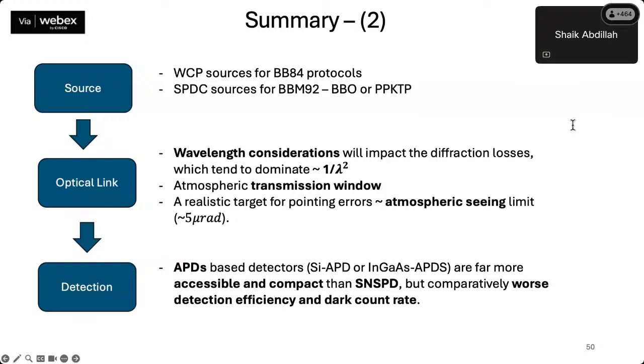So there is a follow-up question. Can we use existing optical infrastructure for quantum data also? Up to a limit. We are attempting to use the optical infrastructure in Singapore, but we are very fortunate because Singapore is very small. So the distance between existing nodes is only a couple of tens of kilometers. Because of the high attenuation of optical fiber, in the absence of quantum repeaters and quantum memories, using just the optical infrastructure is very limited.